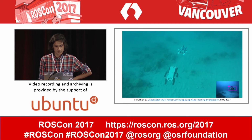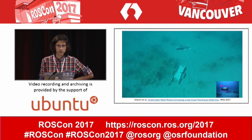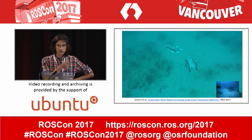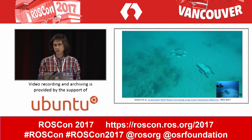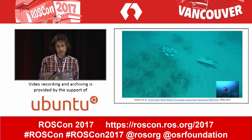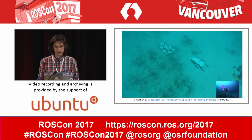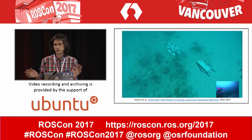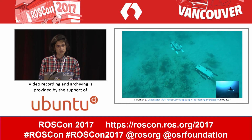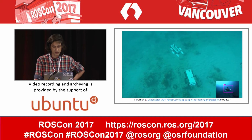Another application that we're going to be presenting at IROS is convoying with the robots. The idea is that we can have one robot that deals with global localization using an acoustic sensor, and we let a robot behind it carry another sensor payload and not worry a lot about localization or control. We just put in there a really simple tracking controller, a reactive controller to follow the leader.